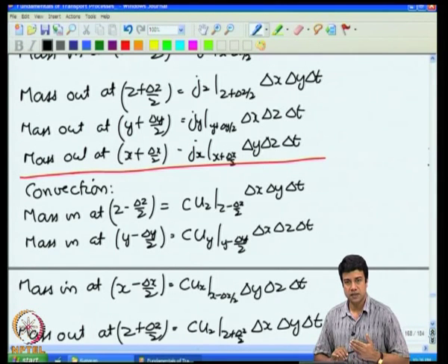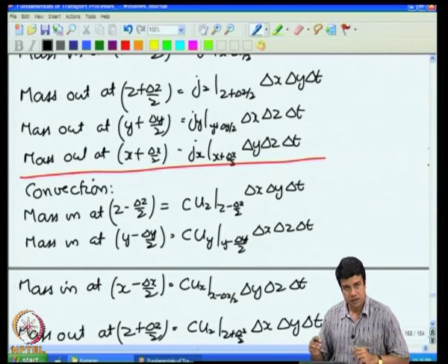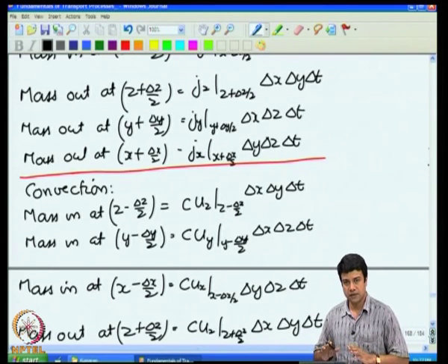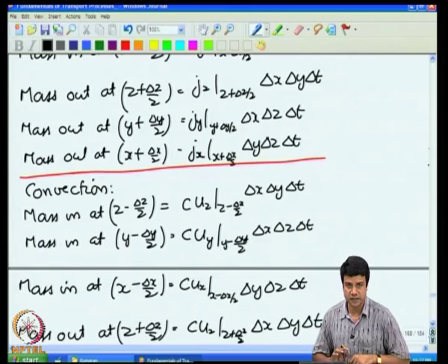In this particular case, I will substitute C times Ur for Jr, C times U theta for J theta, and C times U phi for J phi. So, I will first derive the expressions for the fluxes and just write down the expressions for the convective parts just by analogy.